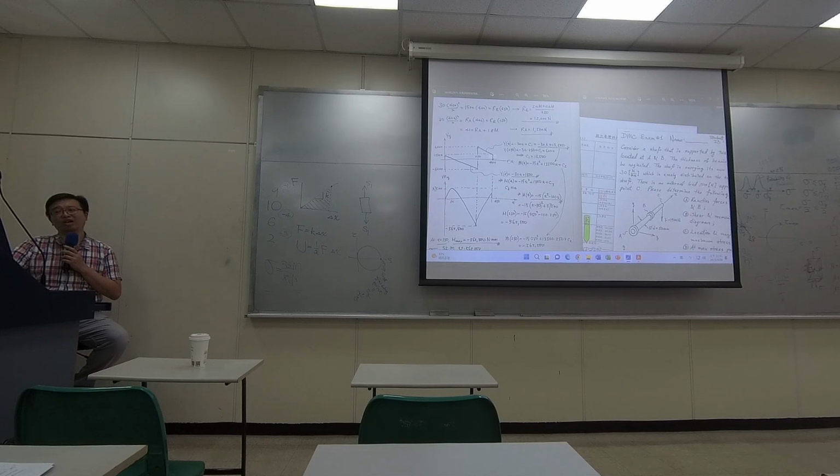I think it would be right because at the end we have a 1,500 Newton force, and this gives me 0 at the end. Usually the shear diagram goes back to 0, and that's usually right. Here is positive 1,500, going through all these, and then going down 1,500 and reaching 0. So then you can tell it's balanced. Okay, so yeah, go ahead.